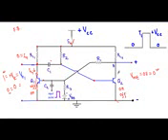Therefore I can disconnect the collector and emitter terminal from our original circuit. The collector current IC2 will be equal to 0, therefore the voltage drop IC2 RL2 will be equal to 0. That means the voltage VCC we are applying between this terminal and this terminal will appear across the collector to emitter ground terminal of the transistor Q2. Therefore our output voltage will now be equal to VCC, or at logic 1.